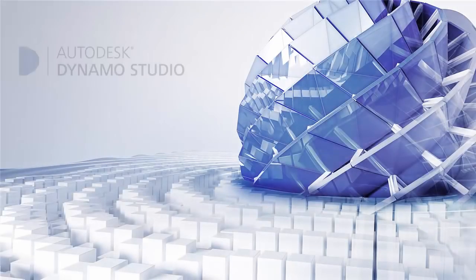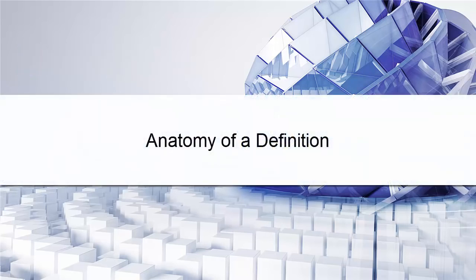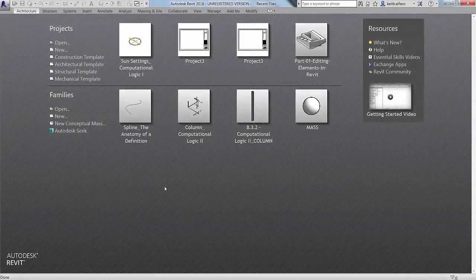In this lesson, we'll take a closer look at the program elements used to define, interface, and connect a Dynamo definition to a Revit document. Before working in Dynamo, we'll have to make several decisions about whether the definition is for a project or family document. For instance, if you are looking to automate the placement of Revit families or manipulate project parameters, you'll want to launch a new project document.